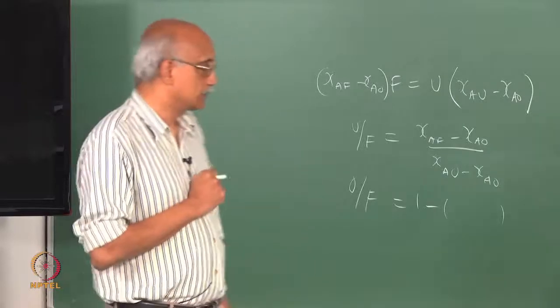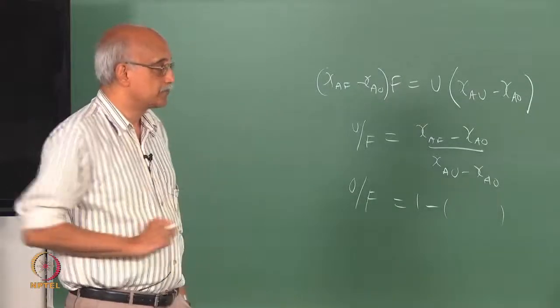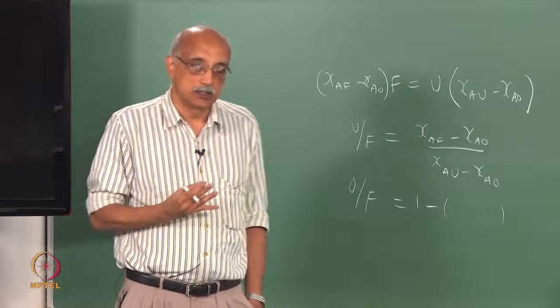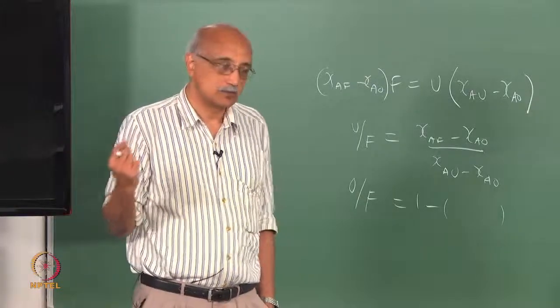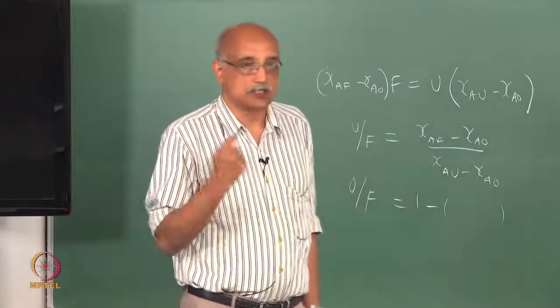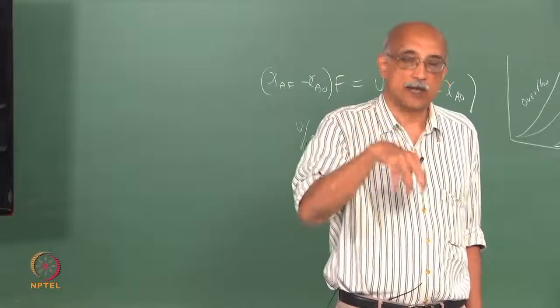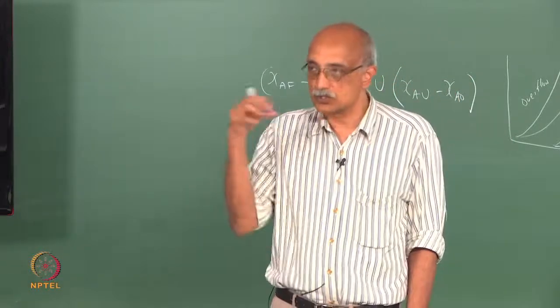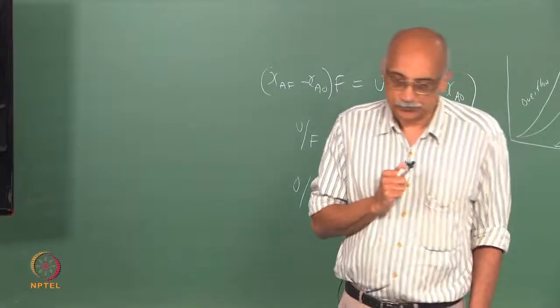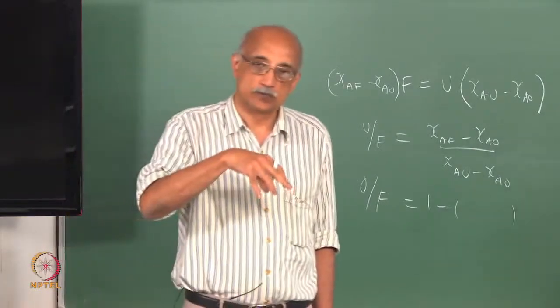But one of the things that you need to look at is what does screen effectiveness really depend on. This is a mathematical representation based on data, but if you are a designer and you are trying to design a screen, how would you try to maximize effectiveness? What dictates the success of a screen? Actually, it is two parameters. One is the number of times a particle impacts a screen, and the second is the screening success based on each impact.